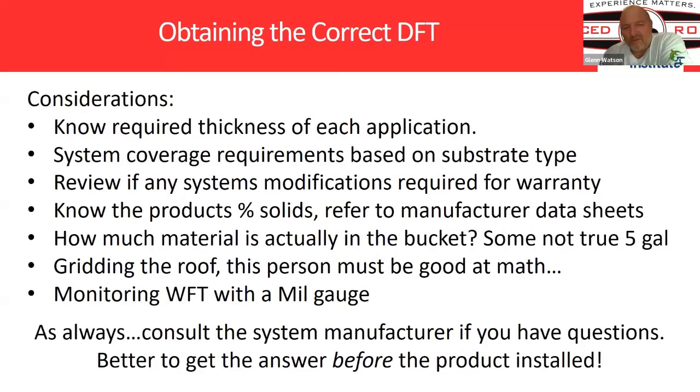You will see some systems that will vary though. You'll see some where the base goes down at one mil and then the top layer or the intermediate layer, depending on the system you're putting down, goes at a different mil. So to speak to what you're saying, Clay, you definitely want to pay attention to that millage. You want to be putting it down at that, not that you're going to be exact, but you want to be monitoring that you're trying to achieve that specific millage, as that millage gives it the optimum cure time or cure window, if you will.